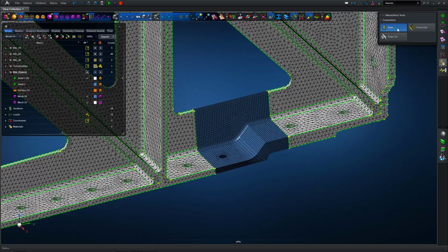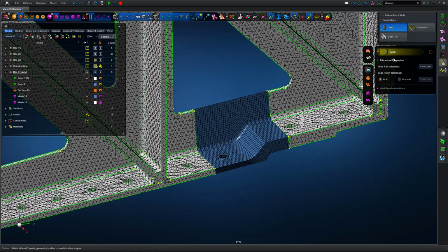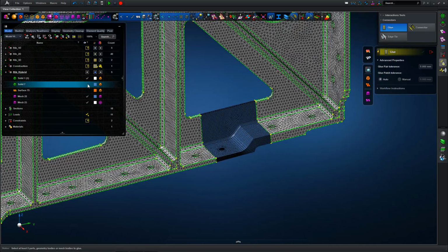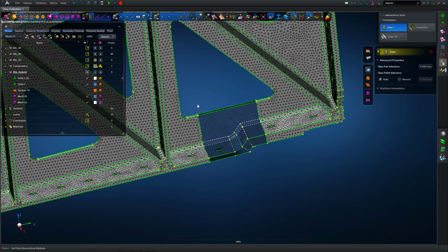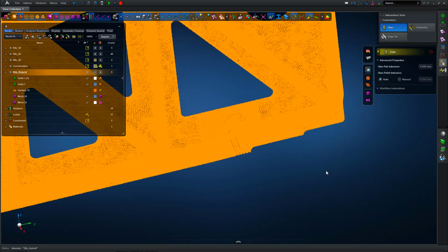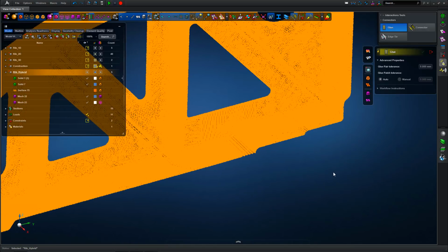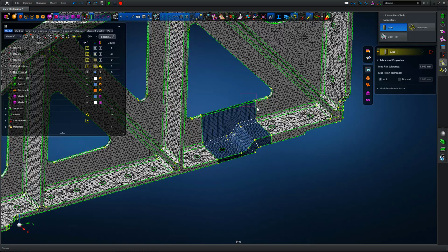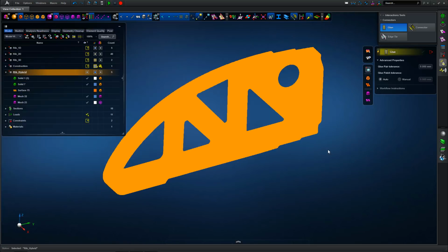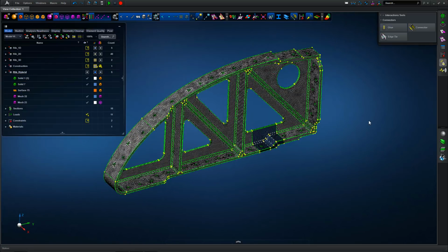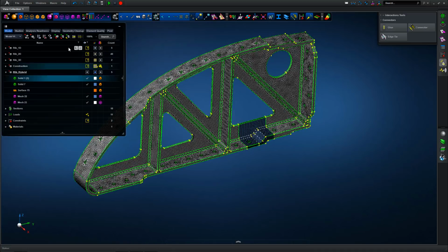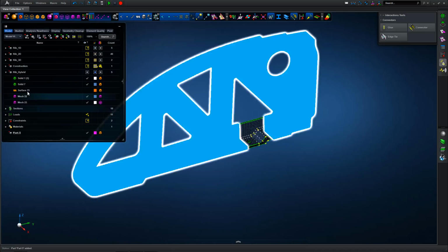Then once we have those two mesh types set up, of course they're not connected in any way through mesh transitioning or equivalent nodes. So we're going to use something called glued contact in Apex, and there are a number of tutorials available on glued contact. We'll run some specific ones in this Apex 101 for aerospace applications.